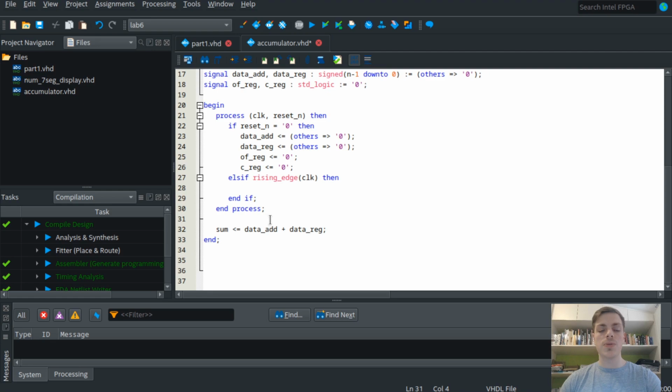So we need to create an extended version, but we can't just extend it by 0, because we don't know if it's negative or positive. And if you extend it by 0, you would change the sign. If it were negative, it would start with 1, so you need to add 1 as the most significant bit so you don't change the sign.